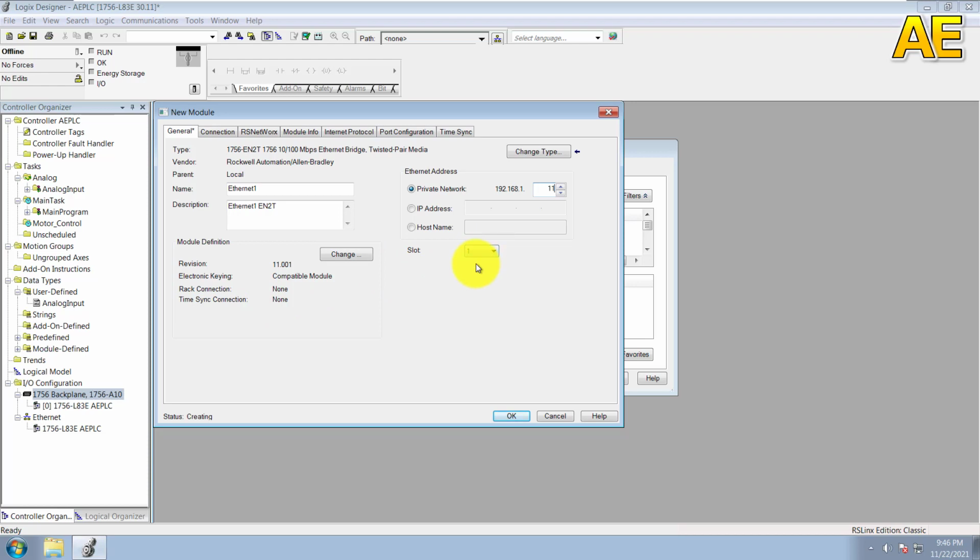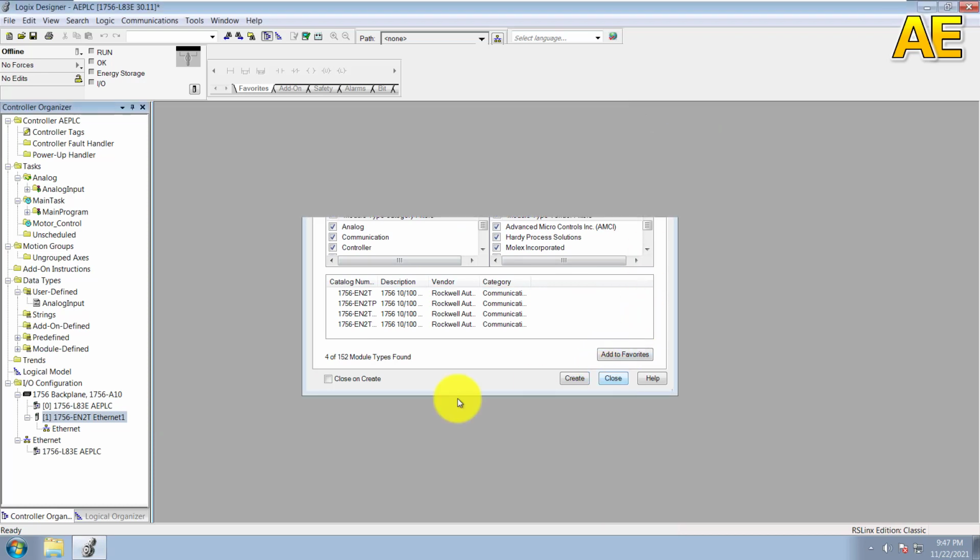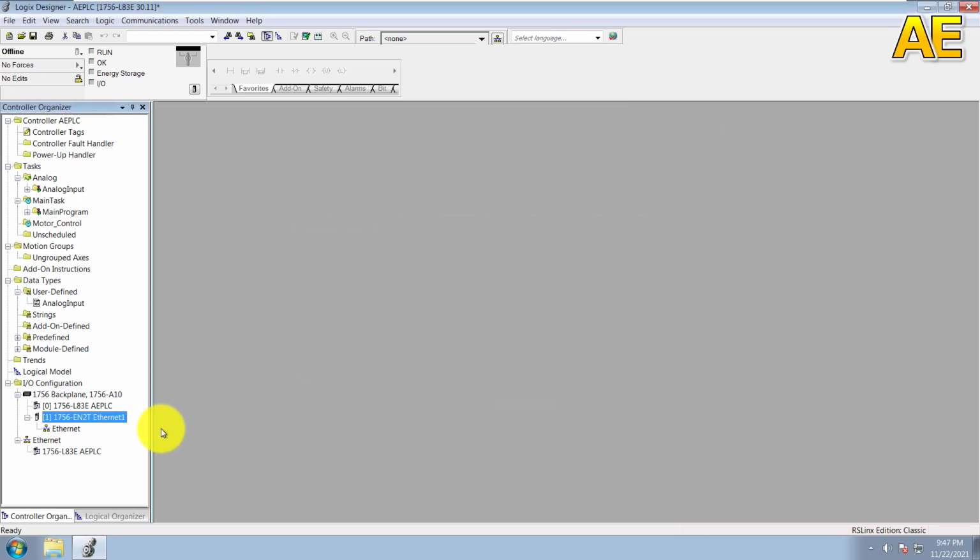If we already have the local Ethernet module, then add a remote Ethernet/IP module. So we are done with the local one. Find the network for the module in the I/O configuration folder in the controller organizer. Right-click the network and click New Module.